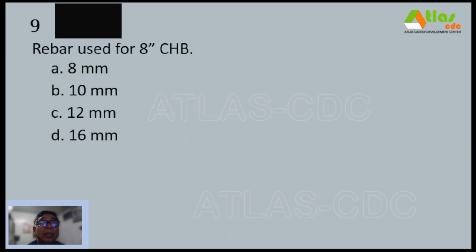Number 9, rebar used for 8-inch CHB. A, 8 mm; B, 10 mm; C, 12 mm; and D, 16 mm. And our correct answer is letter C, 12 mm.